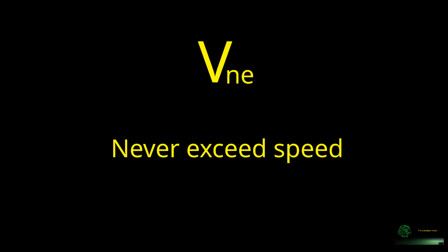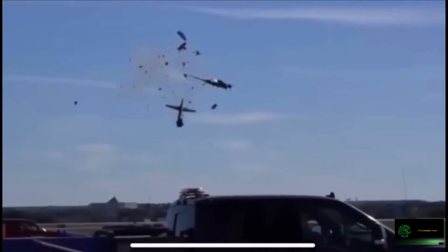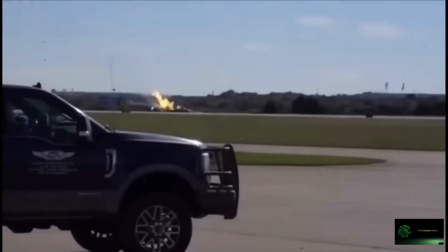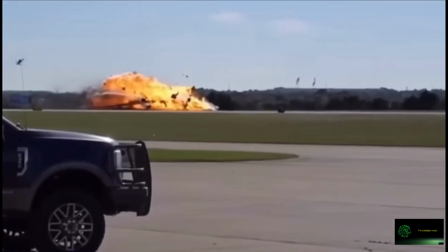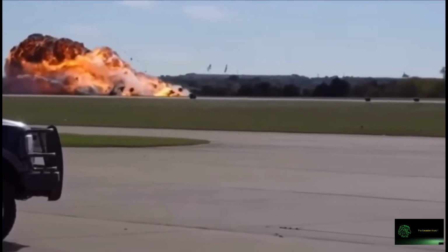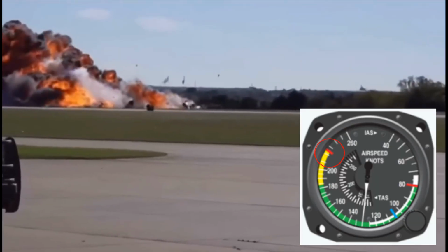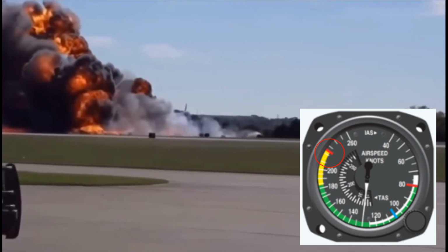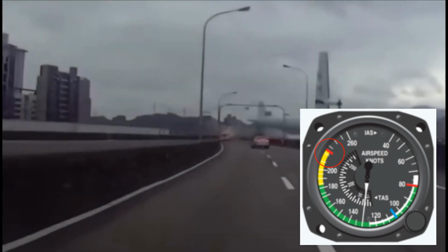VNE – Never Exceed Speed. It's the absolute maximum speed an aircraft must never exceed under any circumstances. Flying beyond VNE can cause structural failure, flutter, or loss of control due to excessive aerodynamic loads. On an analog airspeed indicator, VNE is marked by a red dial line and the needle must never go beyond this limit.